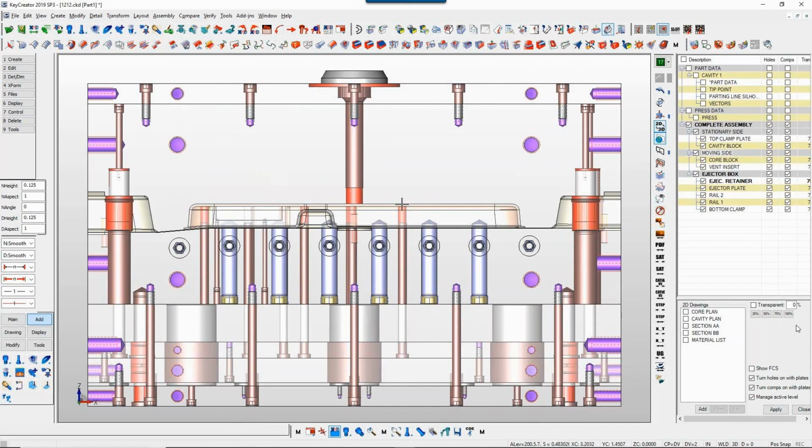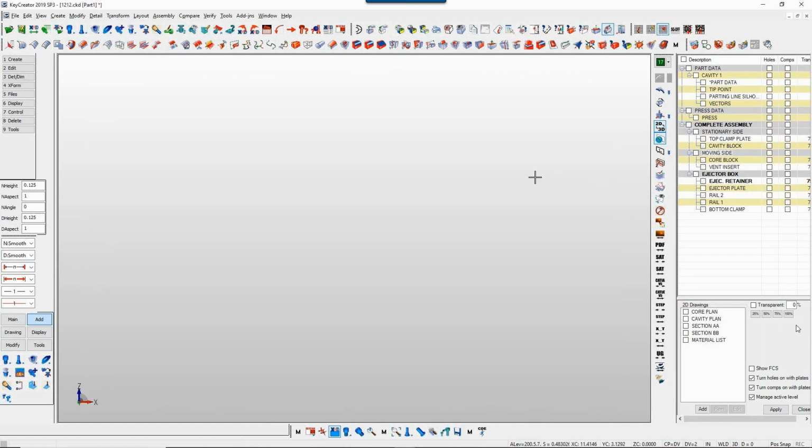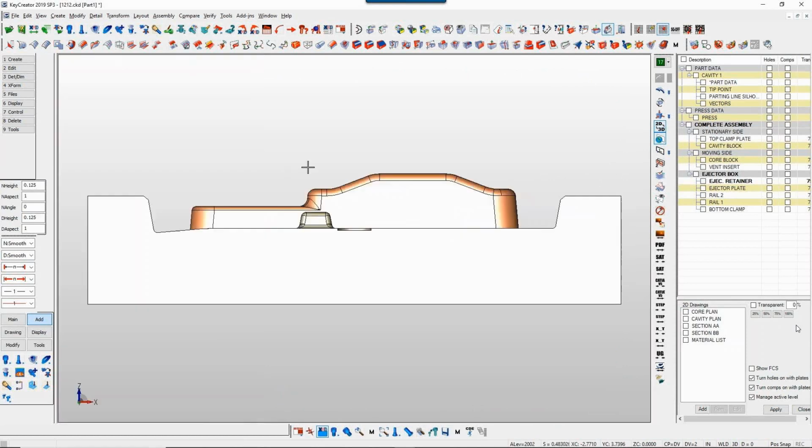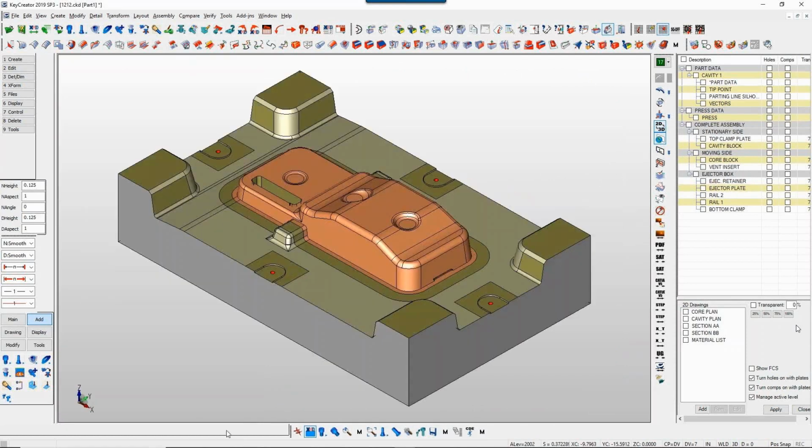It's no longer going to be flat like this. We need more volume or something, and it's going to have this big hump instead. So what we're going to do basically is we're going to obviously remodel our core and cavity blocks, no different than what you would do with any other software, except for the fact that, once again, because we don't care about any parametrics or history-based components of your files, we can bring in that data and right away start unstitching faces and restitching or rebuilding trim sheets or whatever we need to do, depending on what the changes are.